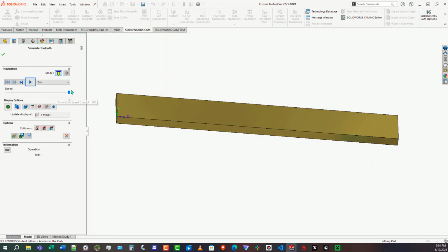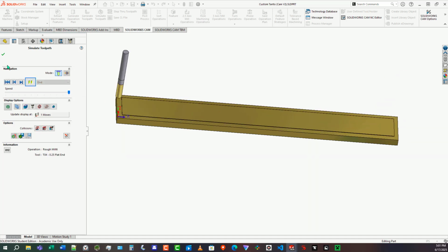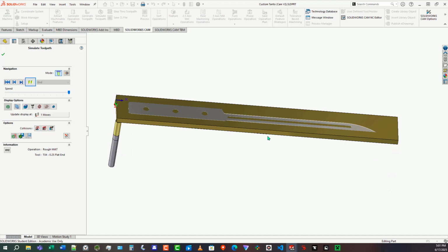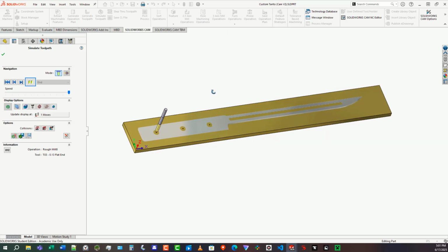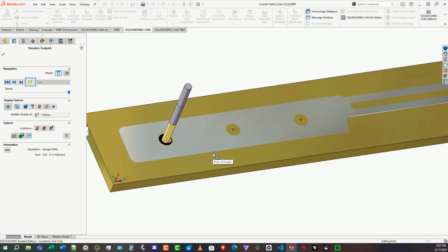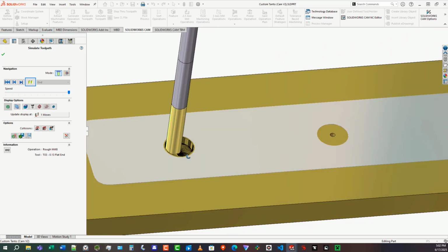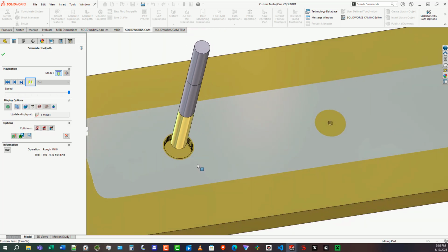The first operation is facing it, and then you just face both sides and then drill. And I'm doing a very slow drilling operation because our end mill, when I cut the aluminum, it clogged up in the center, and I want the cutting to be a lot less demanding on our machine because it's a small machine, and chip removal isn't very good because it doesn't have fluid in it. So this should hopefully help.